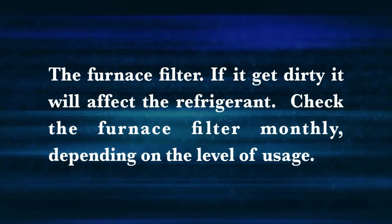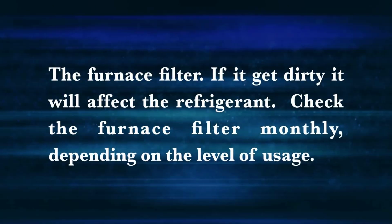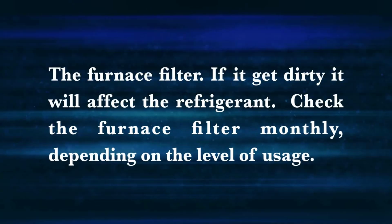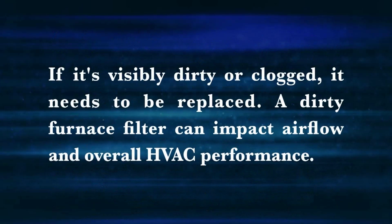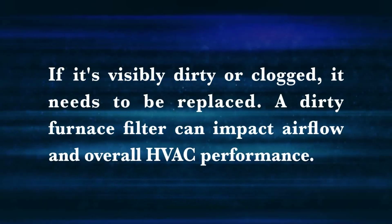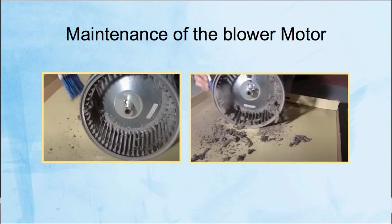Next maintenance step is the furnace filter. If it gets dirty, it will affect the refrigerant. Check the furnace filter monthly depending on the level of use. If it is visibly dirty or clogged, it needs to be replaced. A dirty furnace filter can impact airflow and overall HVAC performance.